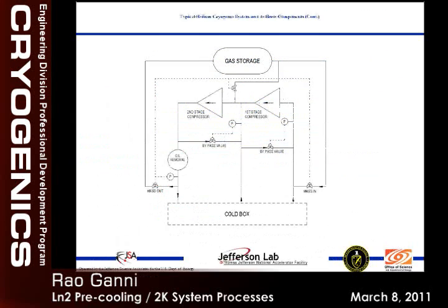And so like we said, compressors compress, and all we do is normally shut off both bypass valves and we allow it to float like what we explained. But when we are commissioning a compressor, let's say this cold box is not there. We are putting, say, 6 megawatts in, and we are running on the bypass. That means these two valves are taking 6 megawatts of power through them. Did anybody think that way?